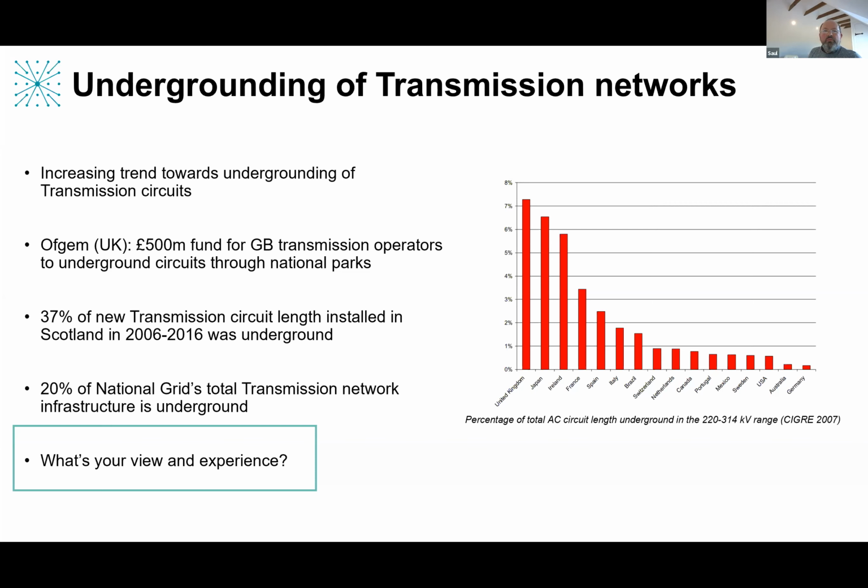Now we're getting to 80% of everyone answering. Then I'll share those with you. There you go. Okay, so again, it seems to me that the kind of predominant challenge is in fault finding, and I suppose that's linked to protection, backup protection, and certainly to auto reclose, because one of the main things, of course, with a cable circuit is that if there's a fault on it, then it's highly likely that it's permanent, and you certainly don't want to auto reclose onto it because that could cause even more damage, and potentially there's safety aspects there.